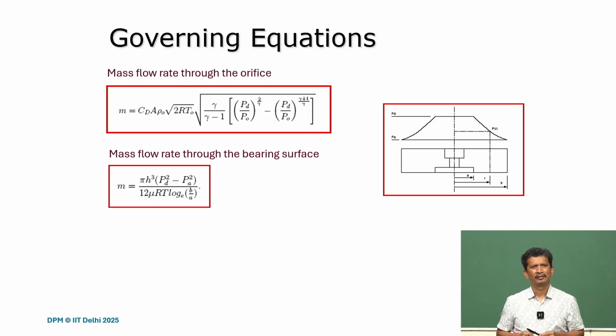So there will be no contact bearings, no friction, zero friction, so maintenance free, no backlash associated with the friction and the stiffness. Since there is no friction, we can say there is no hysteresis, and therefore it's easy to achieve higher precision and repeatability.